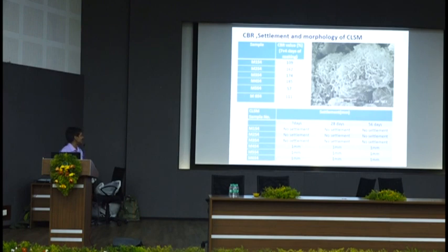And there is another thing I mentioned: in your trench, you are dumping something and after some time it is settling. For that you have to do a small test called the settlement test, at 7 days, 28 days, 56 days. In some of the fills there was no settlement and others had settlement up to 1 millimeter. That also you need to study to say whether you will be able to use it or not.